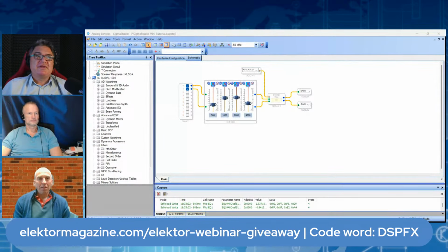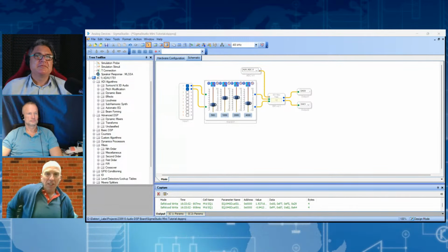One thing I've never dabbled with, Clemens, is I2S, depending on who you're speaking to. Transferring audio around in sort of an I2C formulation, it seems... No, it has nothing to do with I2C. I2S is just a stream of bits. It's just a continuous stream. No addressing or anything. It's just a stream of data and a clock, and it can go very fast. The clock line is separate. You can have several formats. That makes it a bit complicated, of course. There are several formats.